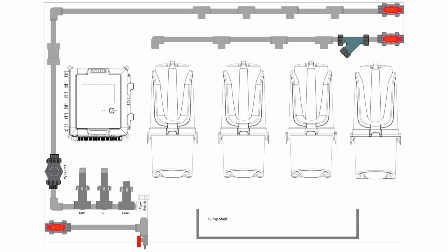A quick question on the makeup water: what sort of pressure do I have to have on that line to feed into the UltraM? It's about a 20 PSIG dynamic pressure at the dissolver. The regulator handles dropping pressure to what we desire for dissolution. So I'd say 20 PSIG is going to be your minimum supply pressure. What's your max before you start running into problems?